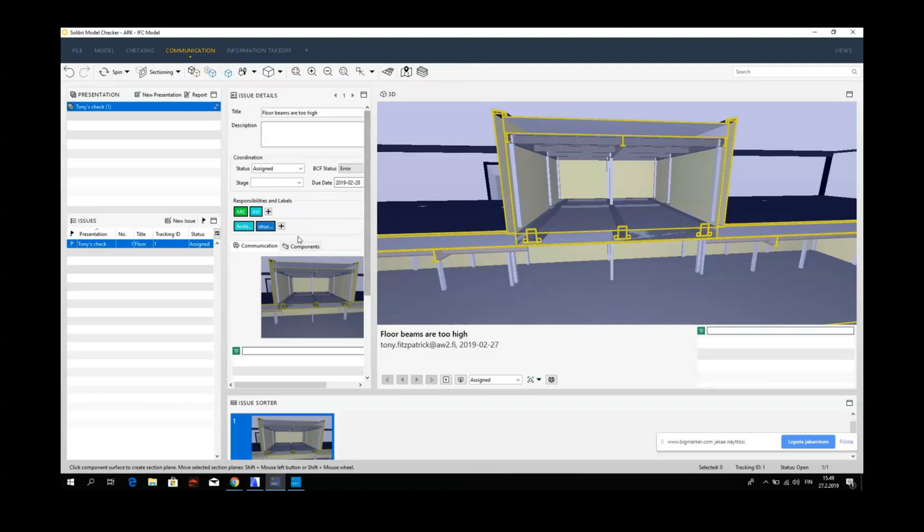Does it work like tags then? Like, can you see if you choose structure? Yeah, basically. It would bring up, so then you can sort by those things. Okay. It doesn't seem to have the ability in Solibri itself to filter elements. Okay. But you can sort them in here. So you can use this thing here to add labels. So when you've got various different labels, it could then start sorting them, so you can quickly go through. So here's the architectural ones grouped and engineering and whatever.